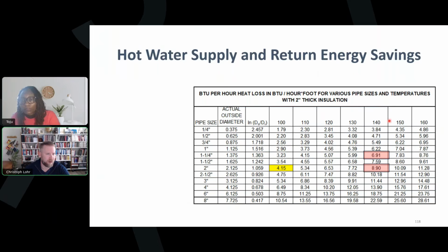Again, we'll just take the assumption of 140 Fahrenheit water. Let's say they're using point of use mixing valves in different locations. They're worried about waterborne pathogens because that building type falls under ASHRAE 188 and other documents such as the ASPE Legionella Design Guide and the NASEM report. So they want to see elevated temperatures in there.